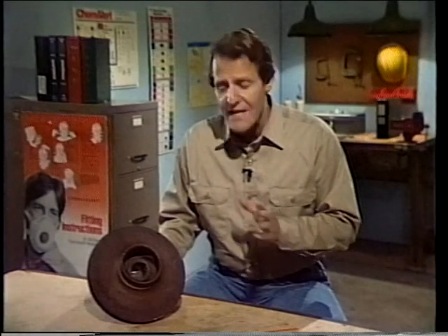Vibration peaks caused by problems such as misalignment and imbalance commonly occur at the rotational frequency. For example, suppose this impeller is out of balance. If the impeller is rotating at 3,600 RPMs, then the imbalance could cause the impeller to vibrate at the same frequency. In other words, the rotational frequency for the impeller would be 3,600 cycles per minute.